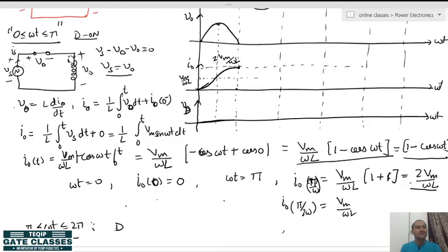In that case, whatever energy is stored in the inductor, if it does not get any path to discharge, then it creates a spark. So here also, if the inductor does not get any separate path to discharge its energy, and you try to forcefully turn off this switch, there will immediately be a spark. That's why whenever you switch off some motor or some inductive load, some kind of spark happens at the switch. Now here, this is not a manual switch which we can forcefully turn off. This is a diode, a semiconductor switch. It cannot turn off until it gets the favorable condition.